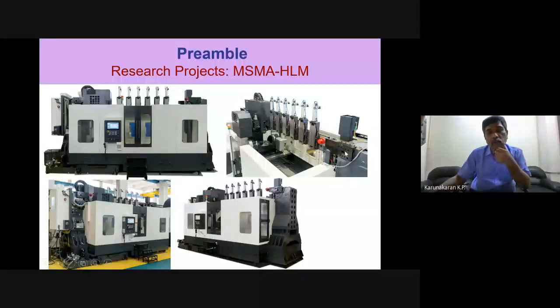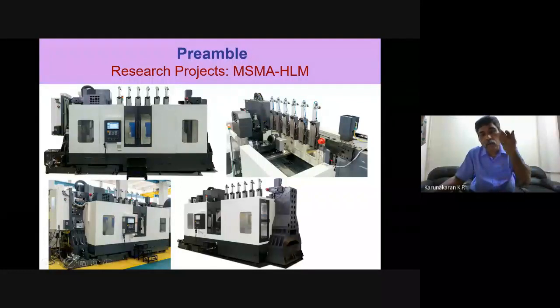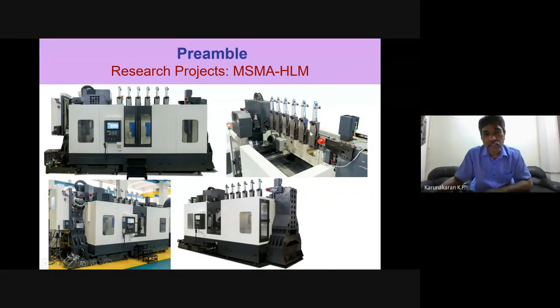This beam is more than 3 meters long, housing 6 tool posts, which can be retracted or lowered by a pneumatic spindle. So the retraction and lowering traverse is about 300 millimeters, and the entire beam moves up and down over a traverse of 600 millimeters, which is our Z-axis. Now you see here a table which is called a Trunnion table, which is actually the B and C axis for our machine. On this side we have a spindle, on this side we don't put anything, but in future we may put probably friction stir welding on it. Otherwise, in these 6 posts, we can mount maybe a MIG cladding system, we can mount a laser cladding system.